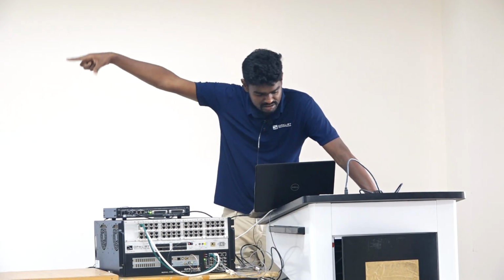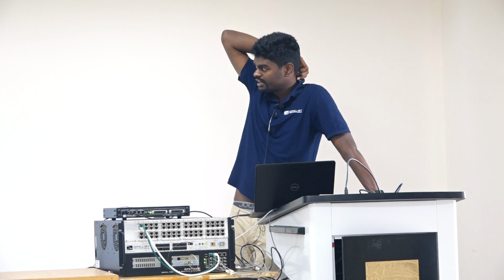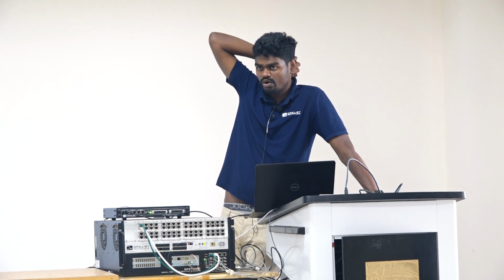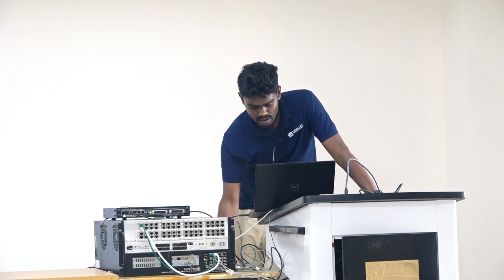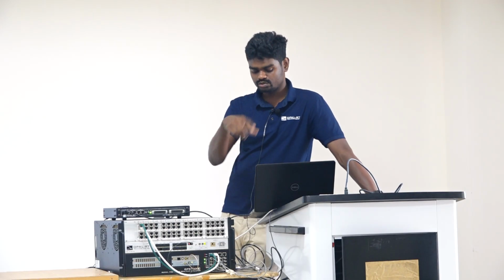You can see there the sign limiter, whatever. That is the model which I have imported. So you need to build, load, and execute here. You have the build option, and you should also add the target. The target is your simulator. Every simulator comes with its own IP address. So your host PC will communicate to the simulator through this,